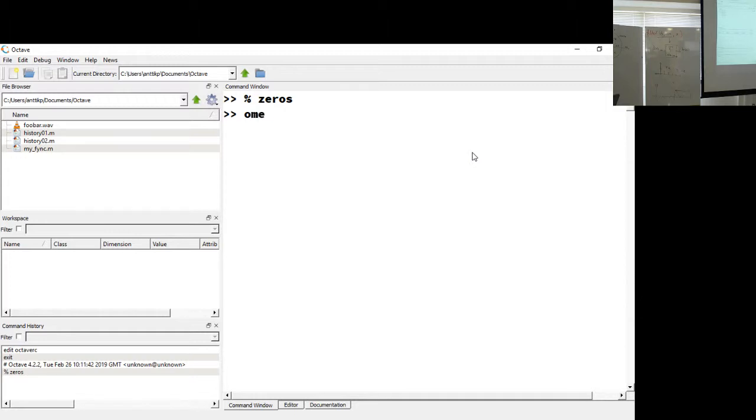Actually, maybe I can just use the angle for the zero would be 2 times pi times 750 divided by sampling rate, 2000. Yeah, that's the complex angle corresponding to this frequency. There.